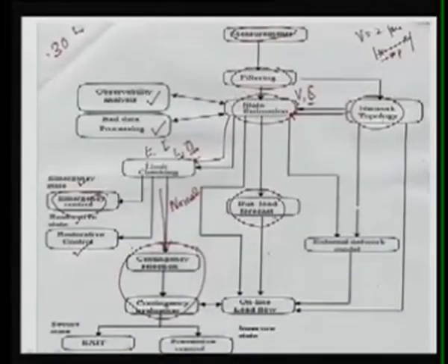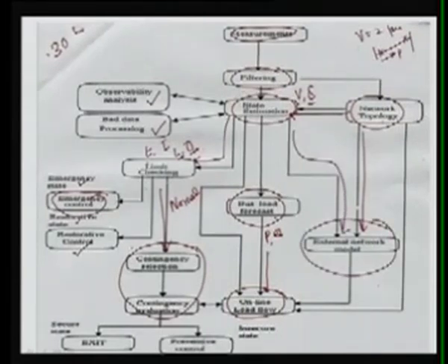So we require some bus data, the bus load forecast, and after getting the load forecast, meaning we get the P and the Q at the various buses, that is used in your online load flow. Here in this online load flow, we also require the system states, the network topology and other information from the state estimation, so that we can form the external network.